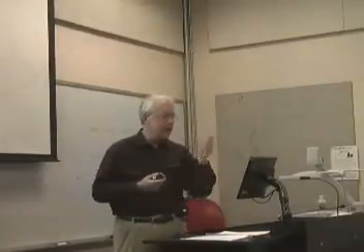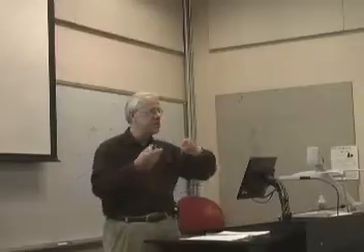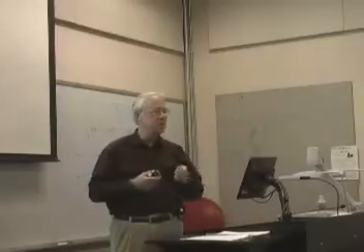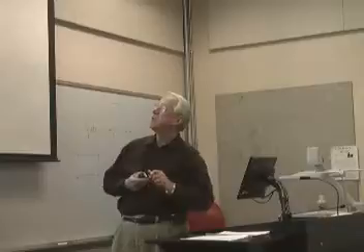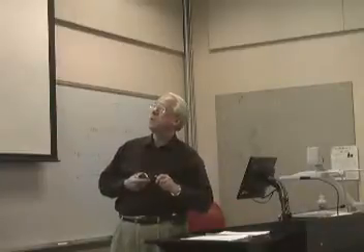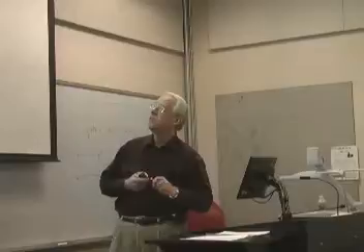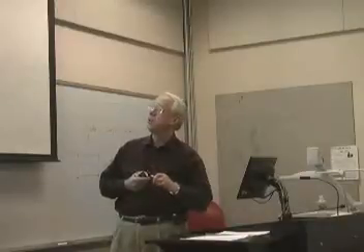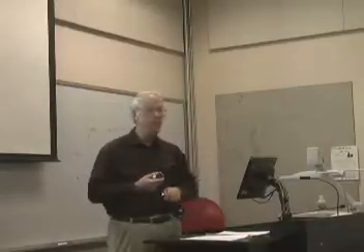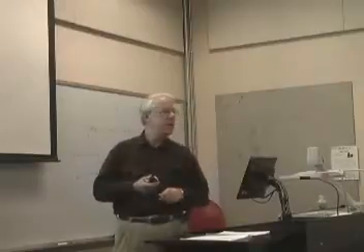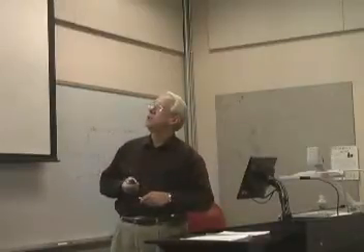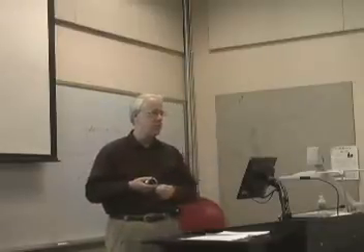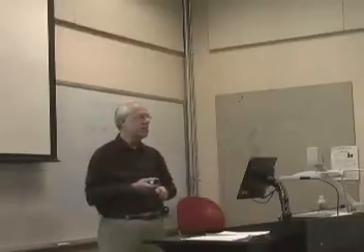So now the matrix, this is the beauty of finite elements, is that you set up matrices, and you only have to do them one time because they're a function of space. Assuming that your elements are fixed in space, you only do it one time, then you're finished. So here's the matrix that would be associated with the time-dependent term. Here's the diffusion coefficients. Here are all the terms on the right-hand side that are given or known. So you can do that easily at one time. So once you've done, then you're free to do whatever you would like with regards to the type of elements that you want to use. Linear, quadratics, cubics, or so forth.